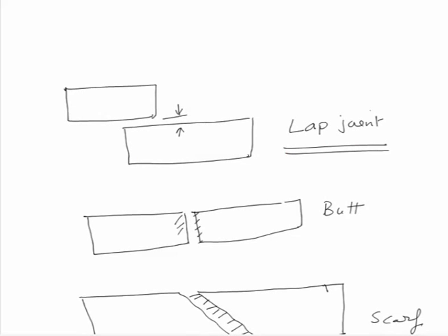When the slanting edges are formed, this helps to have a larger area for the same thickness, and this kind of arrangement is especially used for developing this scarf joint. So, here this kind of slanting helps to increase the area of the joint, which will indirectly help in increasing the strength of the joint. But the lap joints are very common with the braze and the solder joints.